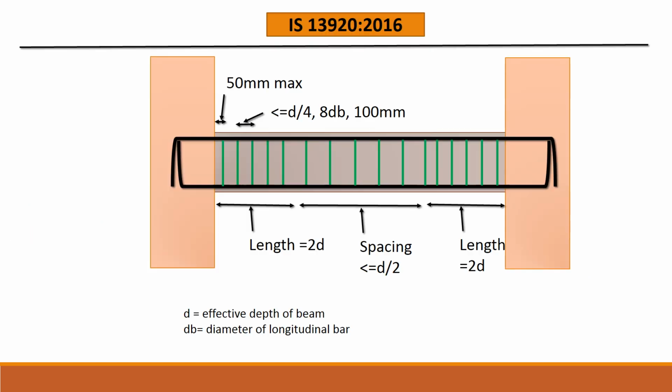In relation to the beams, another criterion that has to be taken into account is how the beam reinforcement runs into the columns. Here there are columns at the two ends of this beam, and it can be seen that the beam reinforcement, both tension and compression, is running into the column. The amount of anchorage that's provided at the ends is equal to the development length LD. The mode of anchorage is also vital here.